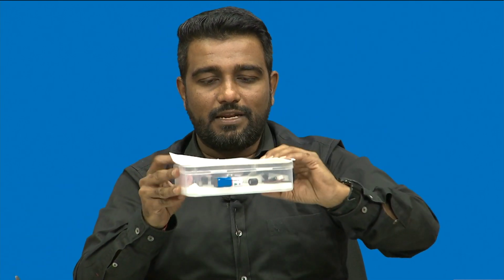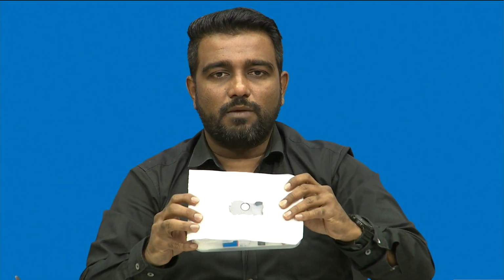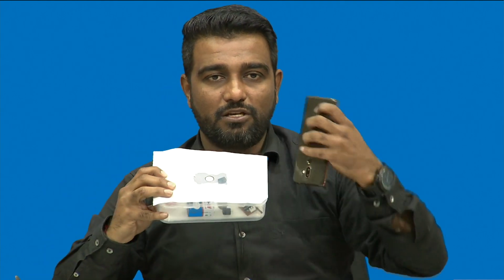What will happen if I load this screen onto a substrate, let us say now I have loaded the screen onto a substrate, right. If I have a material which is my sensing material and if I use a squeegee, understand that there is a sensing material here, if I squeeze it like this on this particular substrate, the material will pass through this particular hole, the remaining area will not be affected.